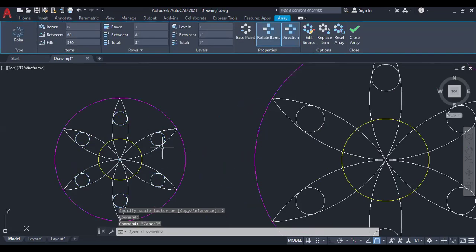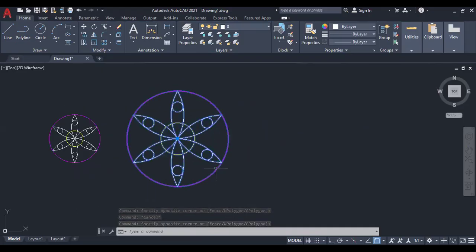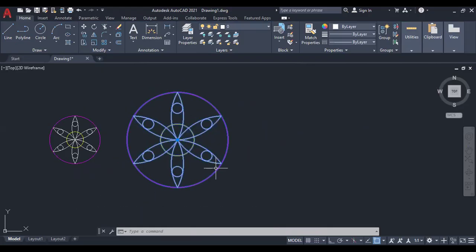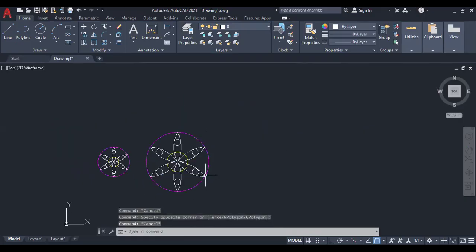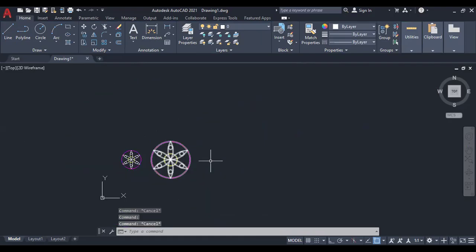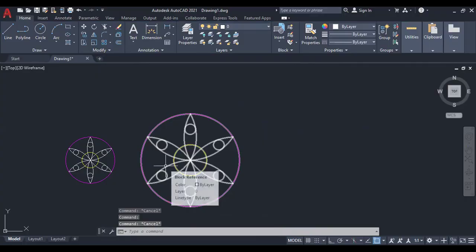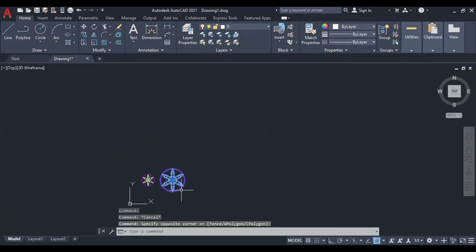This is not the block actually, which one I am keeping next to it. So this is the major advantage of block. You can easily edit, resize and everything. Don't need to scale everything. One more major advantage of this block is, this kind of a chandelier or whatever element I used in a 100 places, there if you update one attribute itself, okay, one attribute itself, it will update everywhere. That I'll do a live demonstration now. I'll select this. Okay.